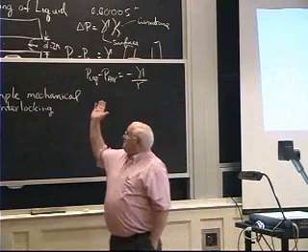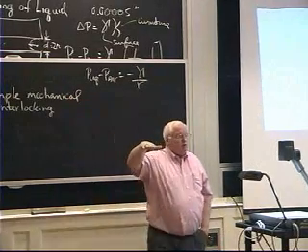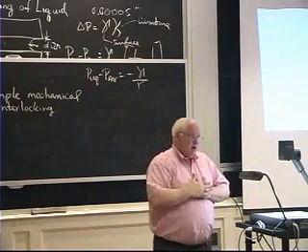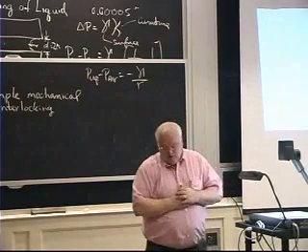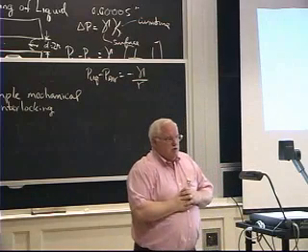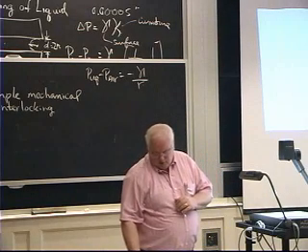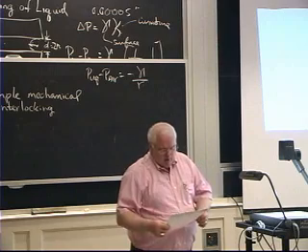Type 1, you want nice smooth surfaces where you can have that liquid in between, and you want to get those surfaces close together and have a very thin layer. If you do the homework problems, you'll get a chance to calculate some of those, and you can get some substantial forces. You'd be surprised at how big some of the forces are. You still have to have lots of bonded area.